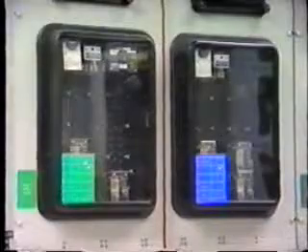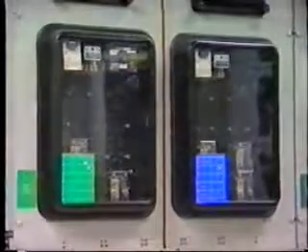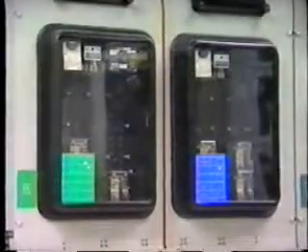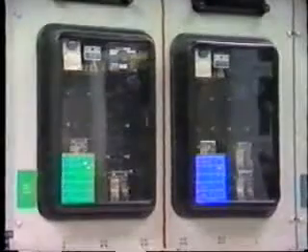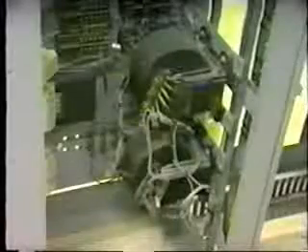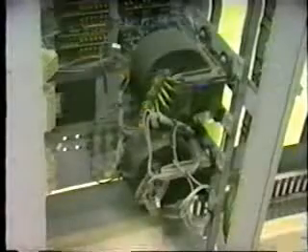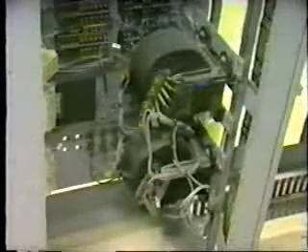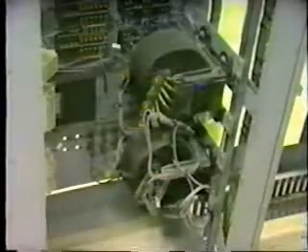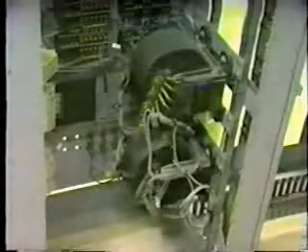As all of the CT ratios are normally identical, the bus differential relays are not fitted with ratio taps. If a particular circuit does have a different CT ratio, then it's necessary to connect an auxiliary CT in order to match the others. Okay, so much for current differential.